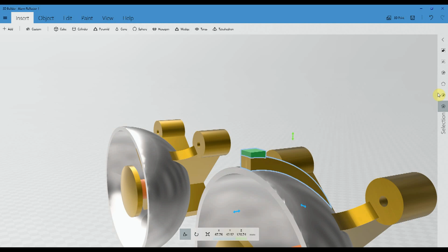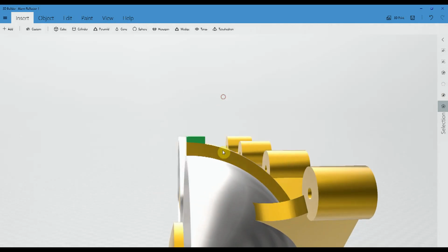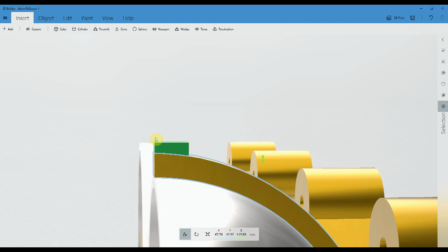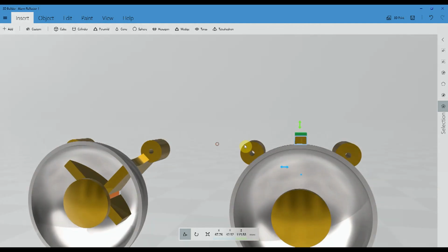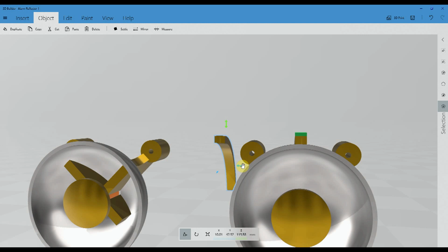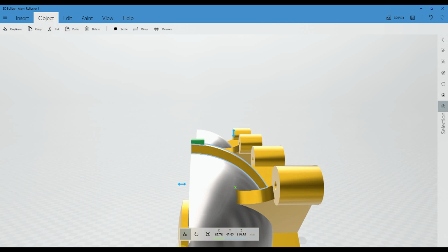and now I've realised I need to have enough structure at the top to put a screw, an M3 screw in, so I'm just adding a cube to that. And then to ensure that it will print, because obviously if you suddenly step out like this on a 3D printer into the overhang, there's nothing supporting it, it won't print properly. You can opt and select to have a support structure made, but that really takes up lots of plastic and loads of time. If I can get away with it, then I will.